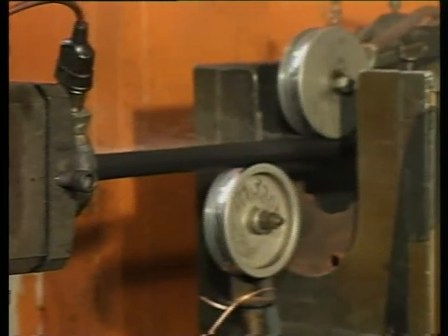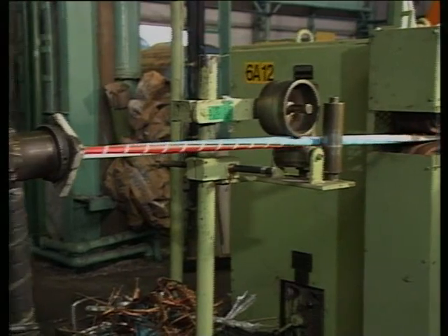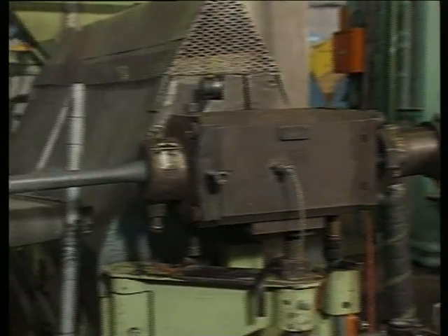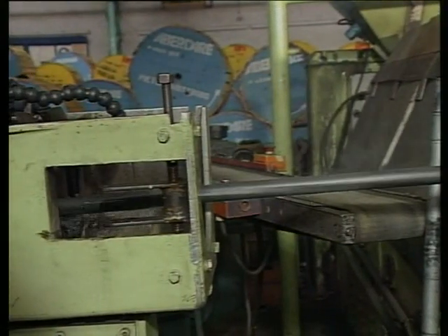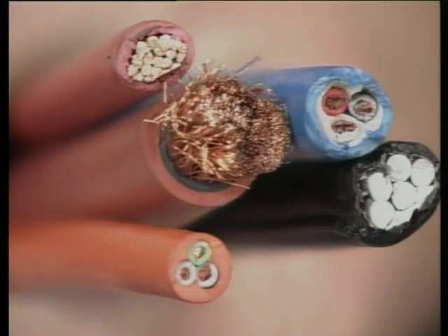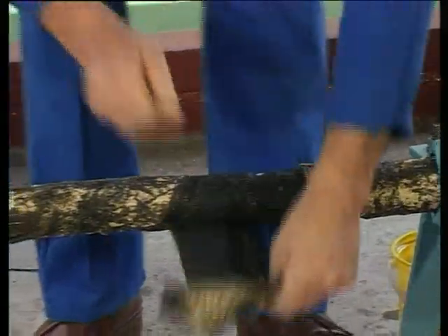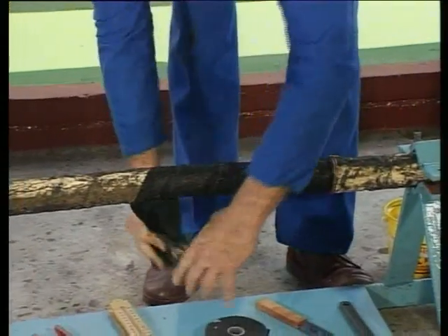Most cables, and especially armored cables, are provided with an outer layer known as the outer sheath or outer serving. The purpose of the sheath is to provide a protective covering to the whole encasement. Depending upon the cable's application and working environment, a sheath may be created from PVC, nitrile rubber, silicone rubber, or even a simple layer of bitumenized hessian, or jute as it is often known.